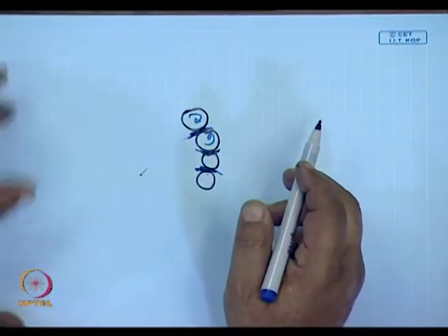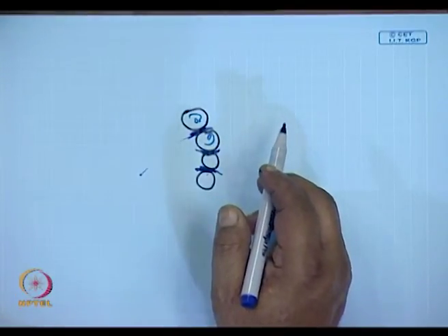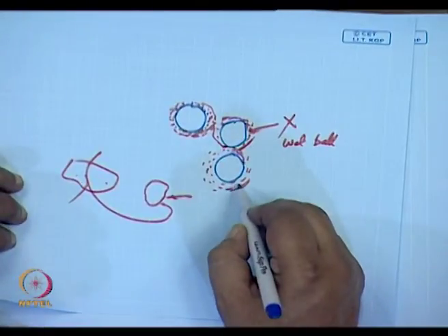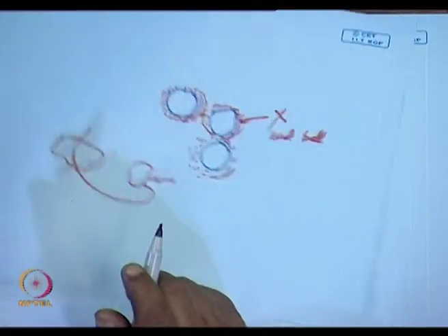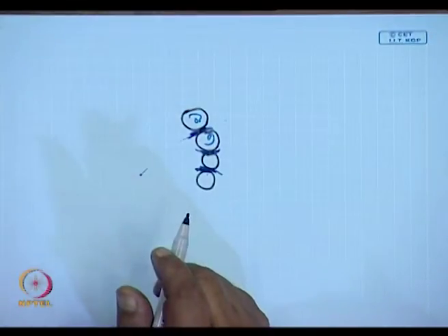Whereas in dry ball milling, we frequently have the problem that the fractured powder is sticking on the surface of the ball. So, essentially, we can have dry ball milling and wet ball milling.